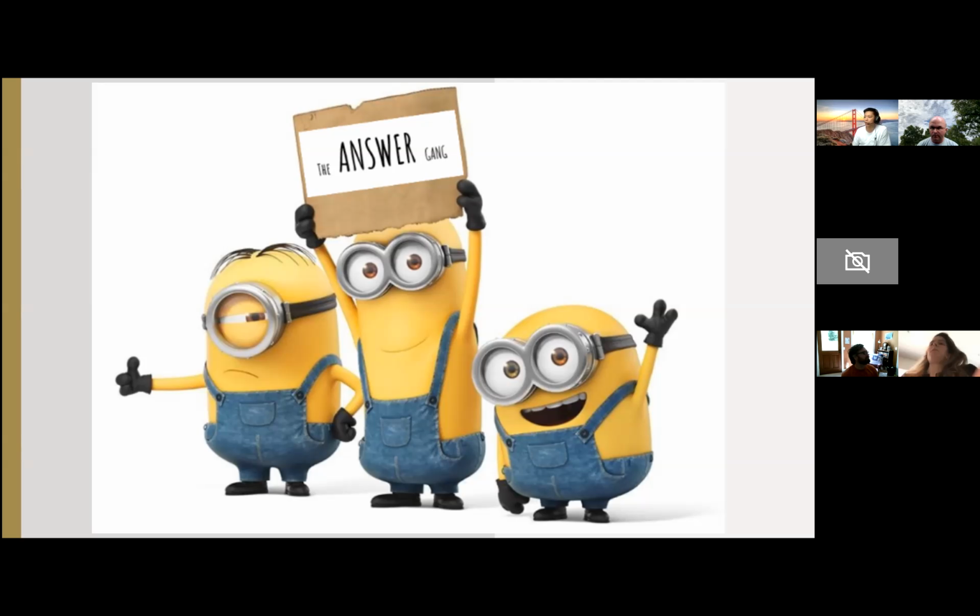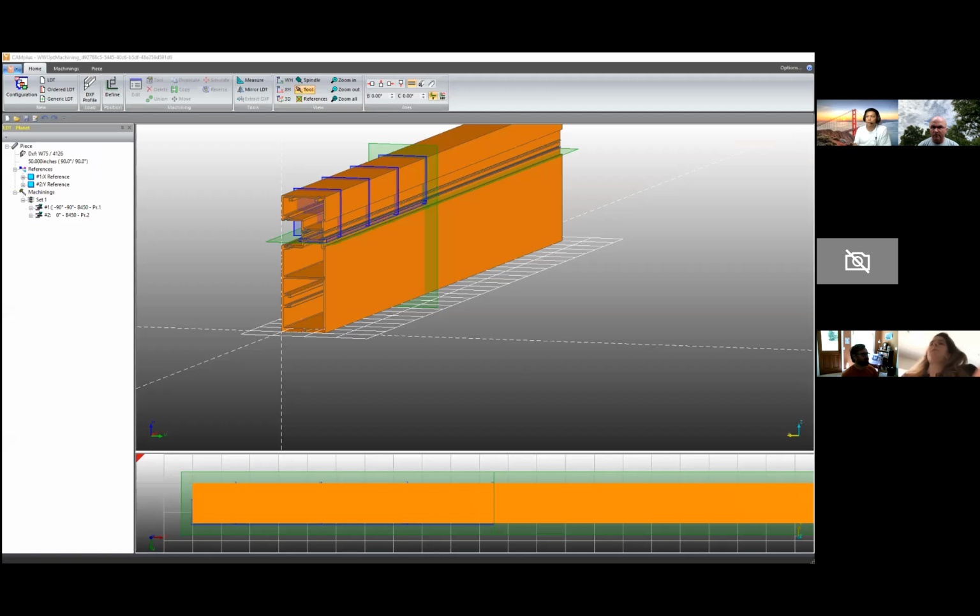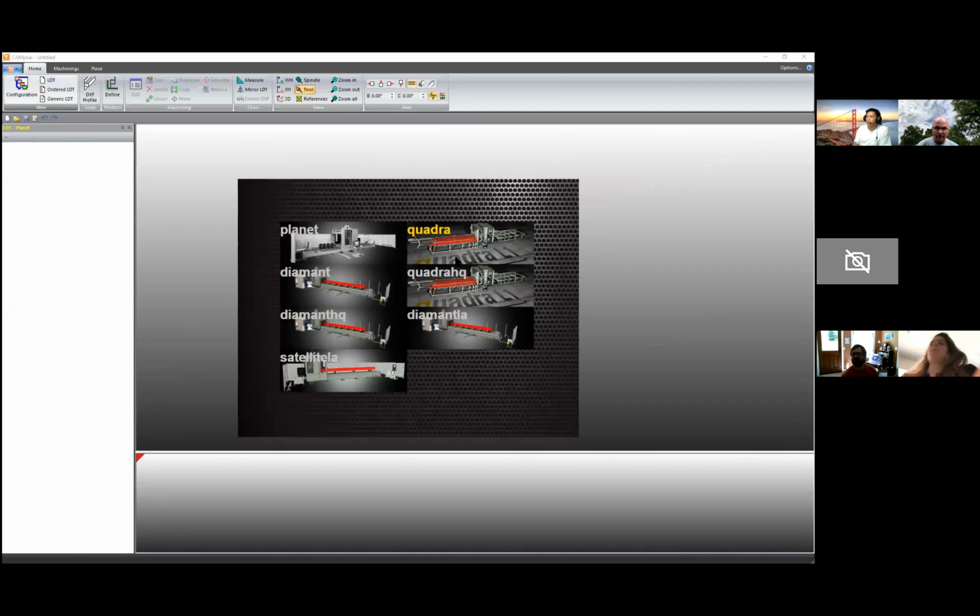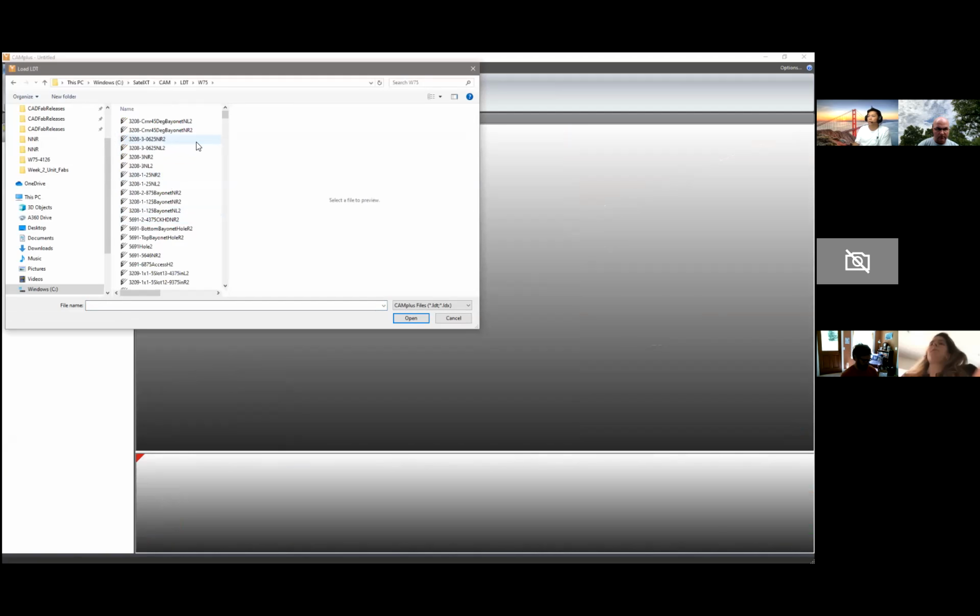This is going to be a new way of fabricating the stack joint because of the miter cut. When there's a miter cut, maybe I can show it to you while I'm trying to explain right now. When there's a miter cut, actually the clamp movement is limited. So what happens is it will not allow us to clamp the short piece because there's a boundary around there for the clamp, so the blade will not cut into it. One good example that I just completed yesterday is Newman.